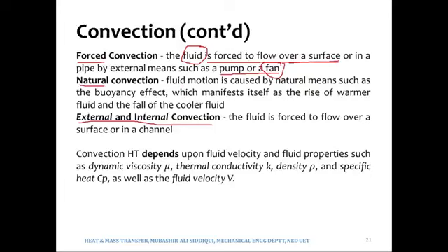Convection heat transfer depends upon a lot of parameters, such as fluid velocity. As I have just explained, the larger the fluid velocity, the more the convection heat transfer rates. It also depends on the fluid properties, such as viscosity, thermal conductivity, density, specific heat, and the fluid velocity, which we have discussed. So let me give you a very simple example of how it depends upon thermal conductivity.